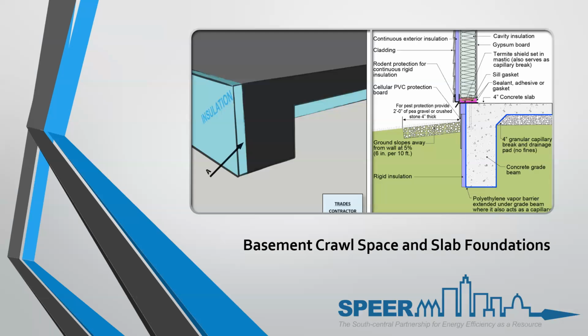Here you can see a diagram on the left showing the slab edge and under slab insulation. I don't believe you have that termite exemption. If it's a heated slab, it needs to be insulated. You may have to still do underneath the slab and not on the edge. But on heated slabs, they must have insulation underneath it, separating it from the ground.